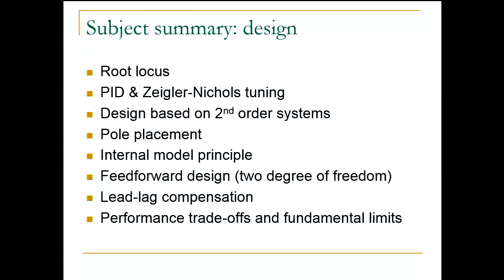We also saw how to do some feed-forward design. It was a non-robust version of achieving zero steady-state errors. And then in the end, we concentrated on frequency domain design. Nyquist was underlying all this as an analysis tool, but in terms of design, we learned how to design lead compensators, lag compensators, and lead-lag compensators in frequency domain using Bode diagrams.